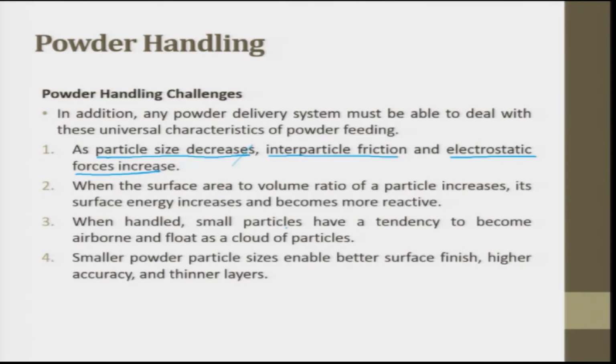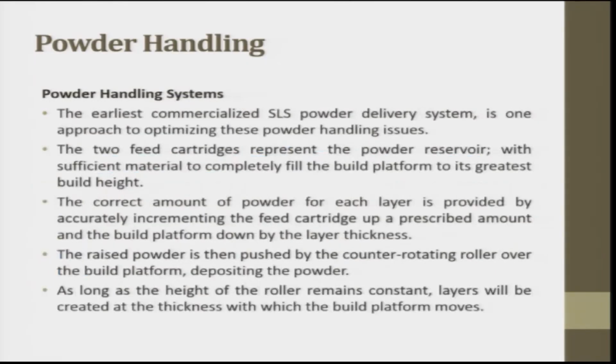When handling, small particles have a tendency to become airborne and float as a cloud of particles. So we should be careful. Smaller powder particle size enables better surface finish, higher accuracy and thinner layers. This is an advantage, but it is also a health hazard, which you have to make sure to manage.